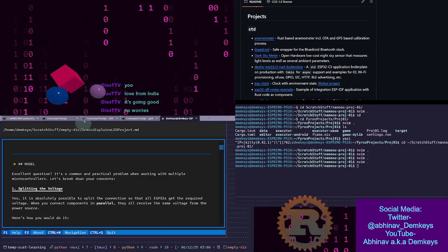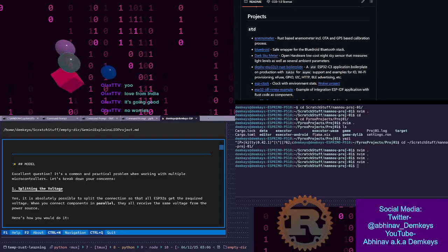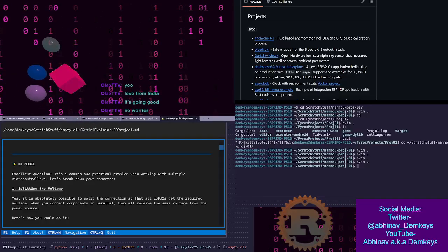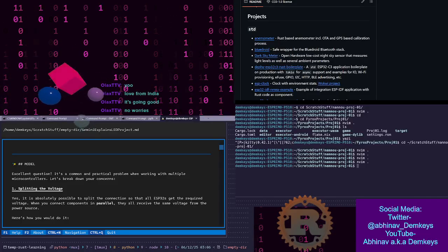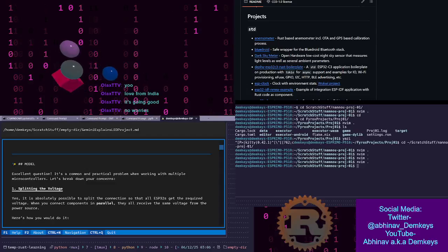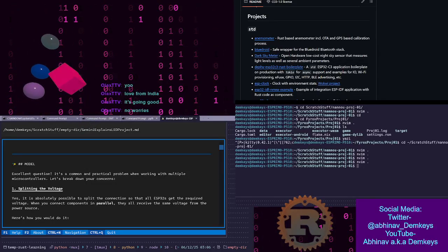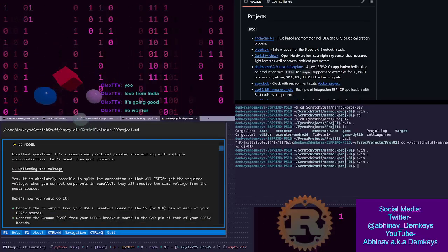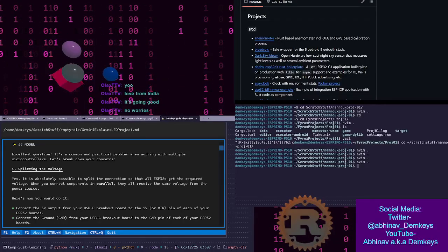But if you're using other functionality within the ESP32, like any of the radio frequency functionality, like Bluetooth or Wi-Fi or something, then it starts to pull a lot more current, and then the current requirement is going to increase. So then if you have like 2 or 3 ESP32s, you're looking at easily 1.5, 2 amps, and that can eventually become bad for the phone charger. Or the charger is just not going to provide enough, and then the ESP32 is going to start to malfunction.